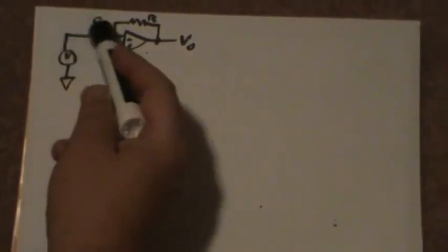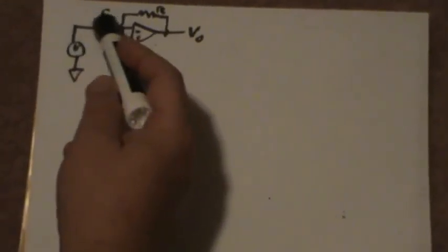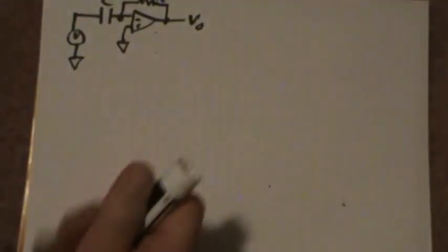So this actually is an example of a high pass system. Low frequencies don't go through. High frequencies will. High frequencies go through perfectly past the capacitor. Actually, the higher the frequency, the easier it will move through. So this is a first order high pass filter.